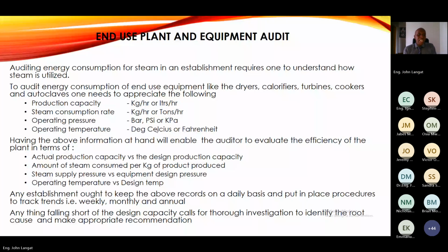So you also need to understand the amount of steam produced per kilogram of products. Once you have the amount, 1,800 per hour, and you are producing 600, you should be in a position to say 1 kilogram of steam will give me 200 kilograms of powder or made tea. Now you need to present that in your report and tell the client, if we take these measures, your production will go up to 300 kilograms of made tea per kilogram of steam. That will be direct cost saving.